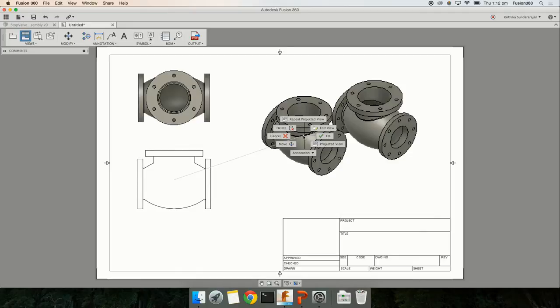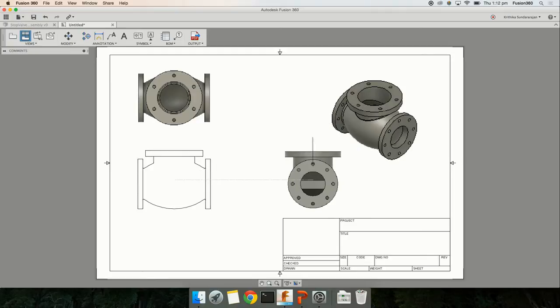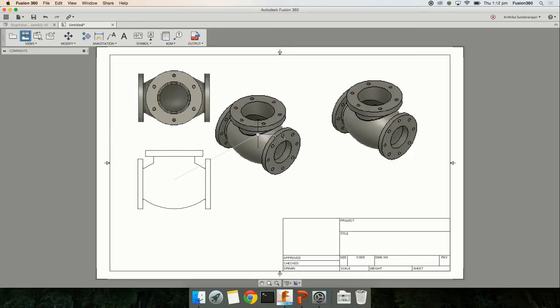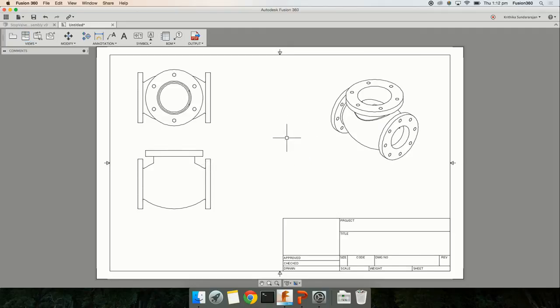The marking menu is contextual, and it contains options based on the command that you're working with. Like, you have OK, cancel, a couple of other commands here. And this one right here is going to lead to a secondary marking menu with some more annotations. And I find this really useful because you don't even have to click and work with it. If you kind of know where the commands are, you can invoke what is called a right-click gesture like that. Just do that. And that works.